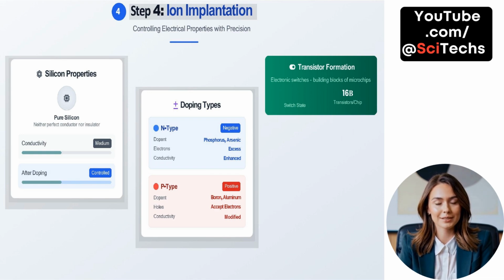N-type doping uses elements like phosphorus or arsenic, which contribute excess electrons, enhancing conductivity and creating negatively charged regions. P-type doping, on the other hand, uses elements like boron or aluminum, which accept electrons and introduce holes, resulting in positively charged regions with modified conductivity. This doping process enables the formation of transistors, tiny switches that control current flow. Today's advanced chips can contain up to 16 billion transistors, each switching states to perform calculations. Ion implantation is foundational in building these high-performance microchips.